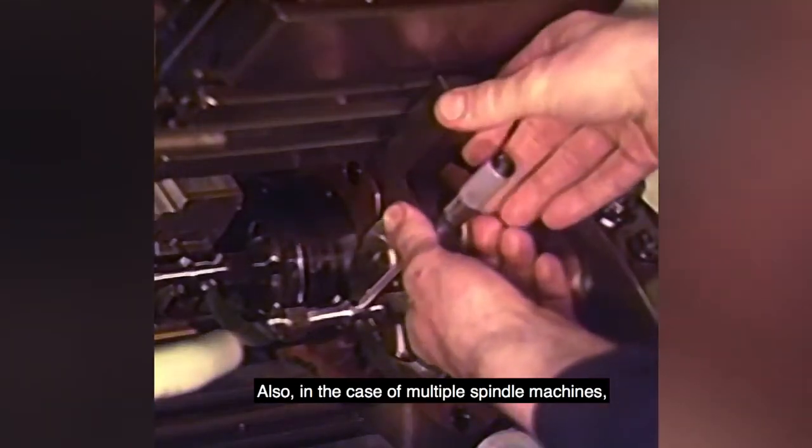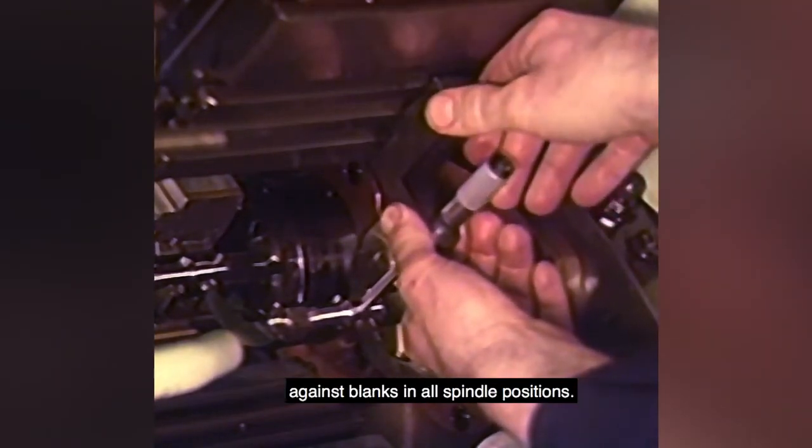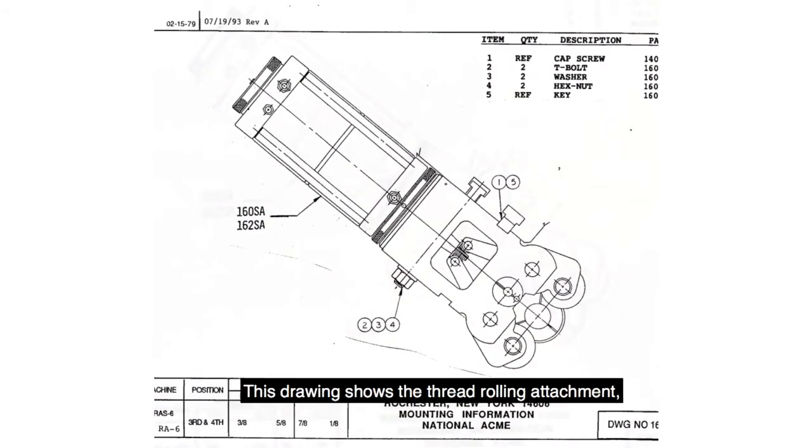Also, in the case of multiple spindle machines, it is recommended that the gauge setting be taken against blanks in all spindle positions. Refer to the attachment mounting drawing in Section 5 of the manual. This drawing shows the thread rolling attachment, the adapter plate assembly if applicable, and all the necessary mounting hardware assembled in the proper configuration on the cross-slide.